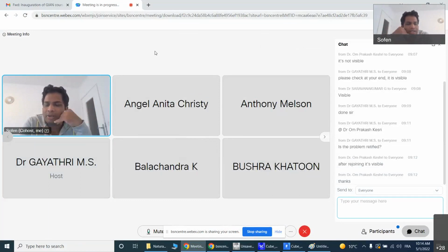You just go for a turbulence model like k-omega SST or k-epsilon, any model you can choose, and do the simulation. Again, k-epsilon has three different categories: realizable, RNG, and standard k-epsilon. Anything you can choose and go for modeling.